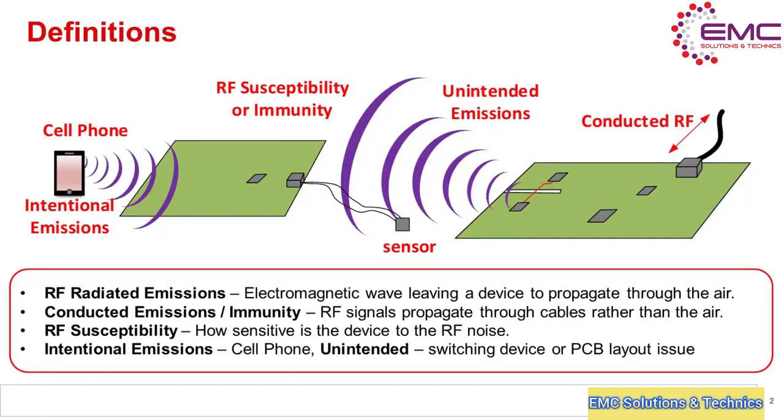In some cases, a circuit that's designed to operate at low frequency can emit high-frequency RF signals. Frequently, this can happen because of poor printed circuit board design techniques. For example, driving a 50 MHz digital communication signal across a gap in the ground plane can cause RF emissions. If these emissions leave the printed circuit board and travel through the air, they are considered to be radiated emissions.